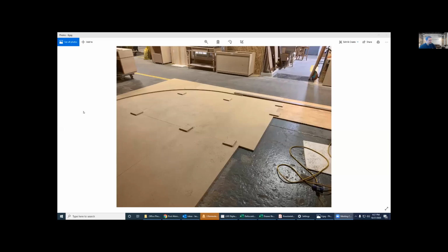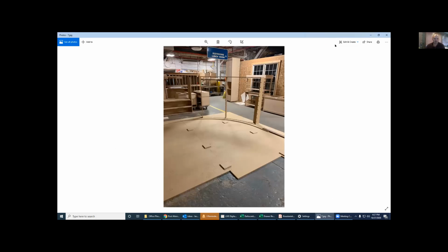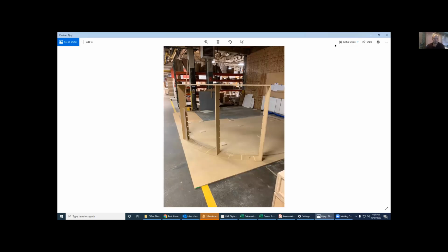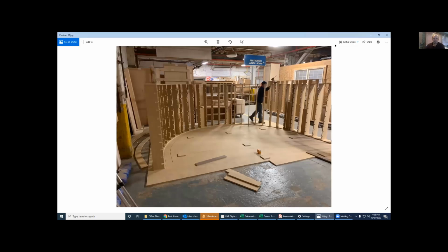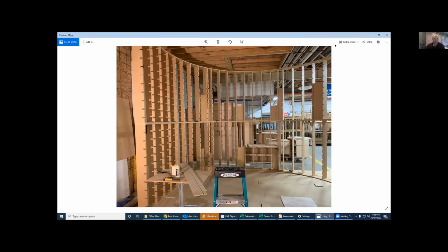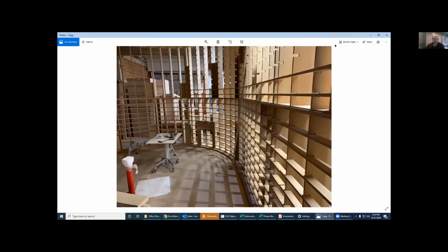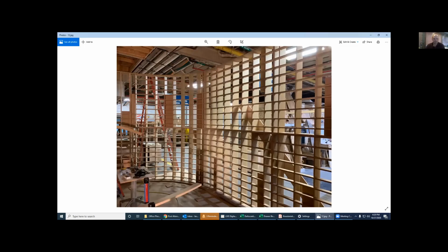Okay, so we just laid out and framed the whole thing, and that's actually my physical template laying on the floor from the site. So we framed the wall up here and squared it up. And then as we added all of our runners, you can see that they're sticking out of the stud wall, like I said, so we're contacting just the face of the radius. And then we laced the whole wall all the way to the top.